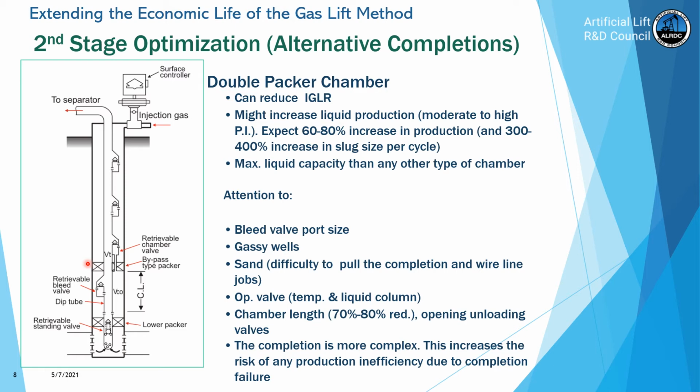So what I did was use wireline operation. I placed a pressure and temperature sensor between the standing valve and the perforated nipple, and then I produced the well for several cycles. At the end of that, I closed the gas injection. I allowed the final cycle to reach the point where the liquid is filling the entire chamber, and then I did 2 additional stops, one in the middle and one at the top of the chamber.